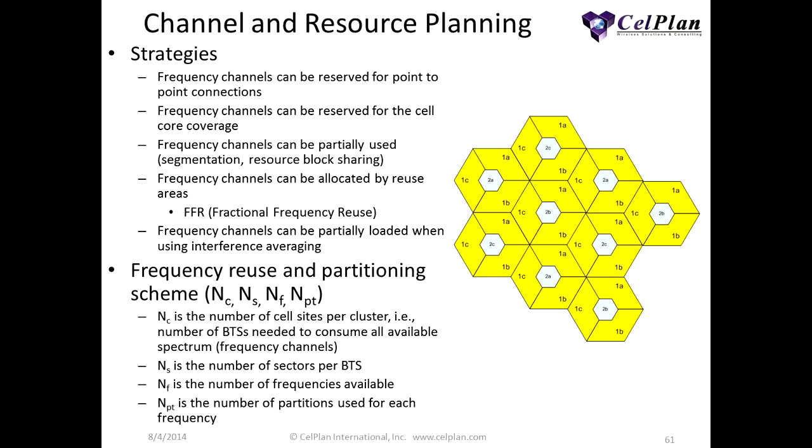So let's speak a little bit about channel resource planning. Of course, to model the different strategies, you have to know what the available possibilities are. Traditionally, we specify what we call a frequency reuse and partitioning scheme. Although LTE was conceived for a reuse of 1, and we will talk much more about this because you will find it over and over, everything was designed with the idea of reuse of 1, and this brings a lot of bottlenecks, but also a lot of qualities.